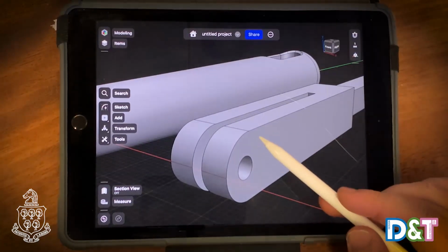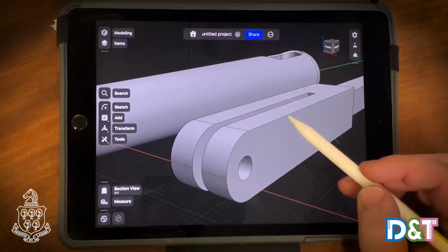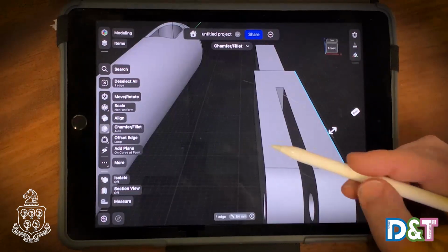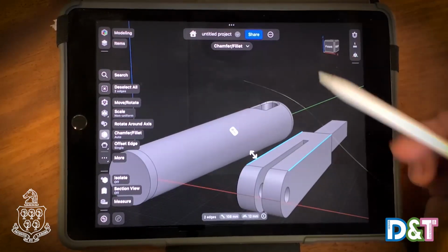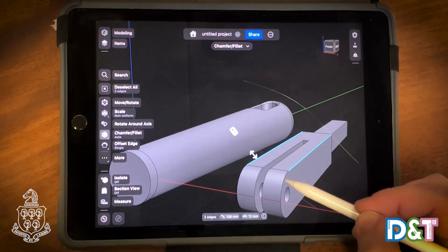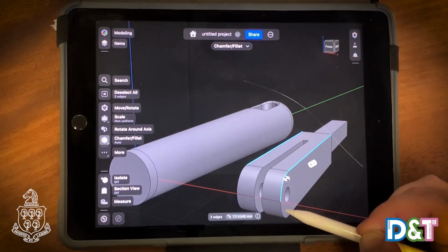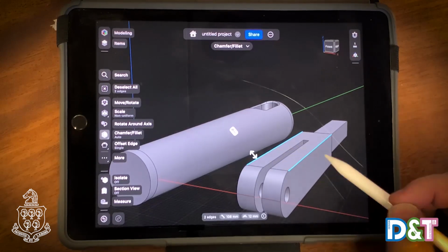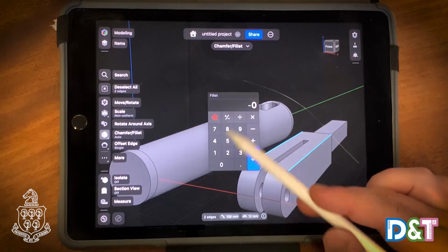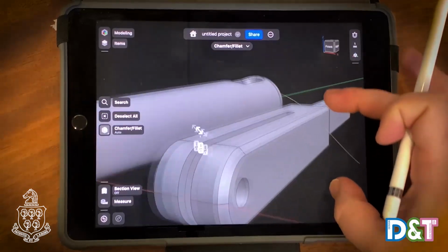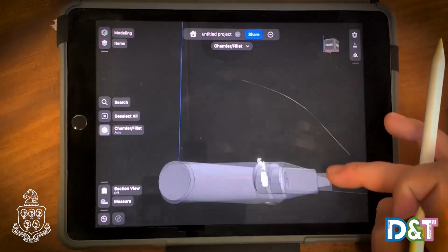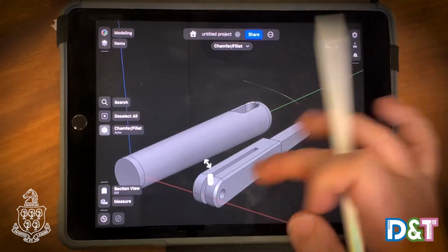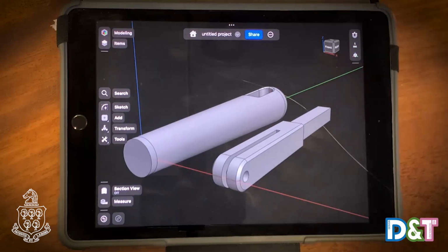And what I think is quite nice is to take these harsh edges of these corners off. So I'm going to select the one here and here. Let's see how this looks. We're going, actually maybe select these ones. I won't select those ones yet, just these two sides, and we're going to do a -1 for a nice chamfer. Oh, that's perfect, so it's gone all the way around. So you've got a really nice shape for the blade holder and tang there. And we're just going to deselect. And essentially that is the blade holder and tang finished.